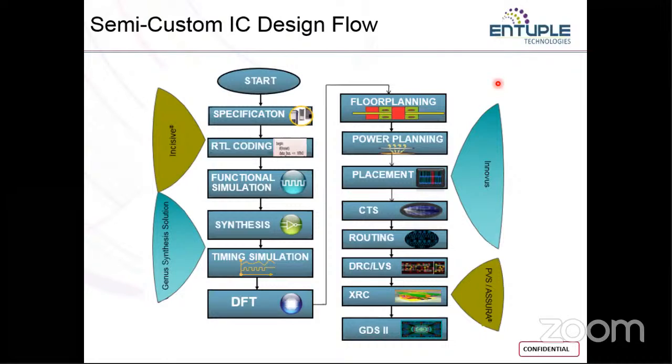See, you have already done the floor planning, you have placed your power lines, you have got your overall design, and you have included the clocks. But are they connected to each other? The answer is no. Until the routing part, your power lines, your core design, your clock signals, everything will be separated from each other. They are not interconnected. So only during the routing part, the overall design gets interconnected with each other.